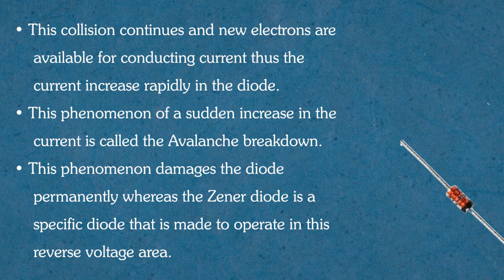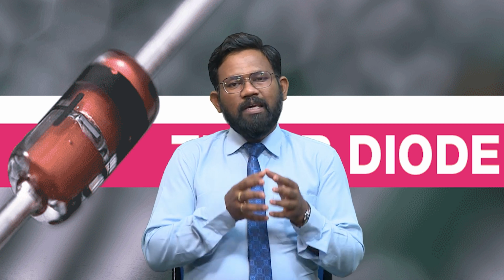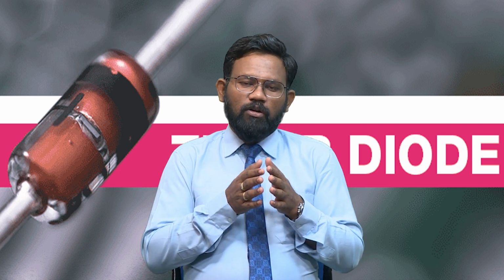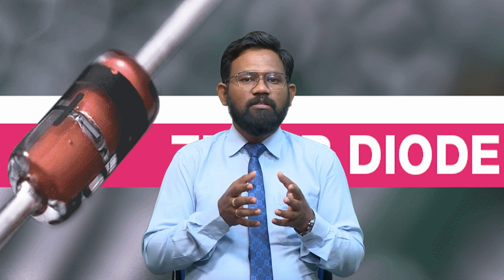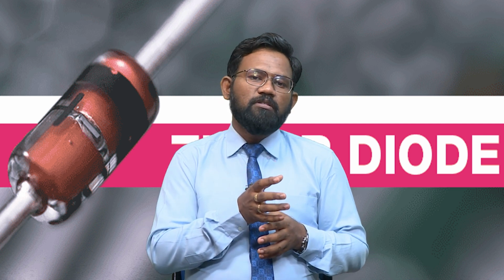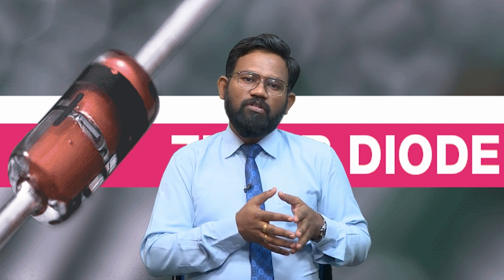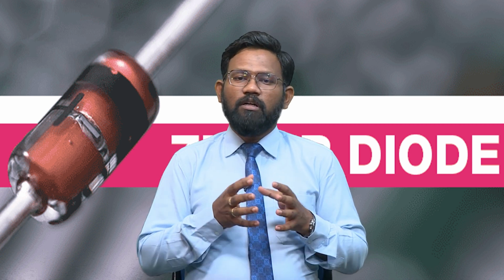Now this phenomenon damages the diode permanently, whereas the Zener diode is a specific diode that is made to operate in this reverse voltage area. The difference between the ordinary p-n junction diode and the Zener diode is the doping level. In a p-n junction diode, the doping level is nominal, lightly doped, and if the voltage is increased in the reverse direction until avalanche breakdown occurs, the very high current which flows in the reverse direction will permanently damage the normal p-n